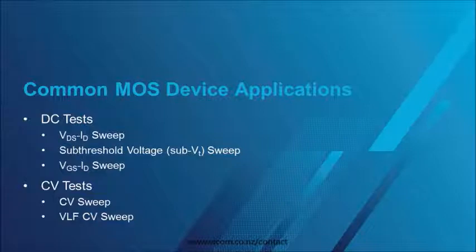Now I'm going to quickly go through some common measurement applications for MOSFET or MOSCAP devices. Some common DC tests are VDS ID sweeps, subthreshold voltage sweeps, and VGS ID sweeps. Some common AC CV tests are a simple CV sweep and a very low frequency CV sweep.